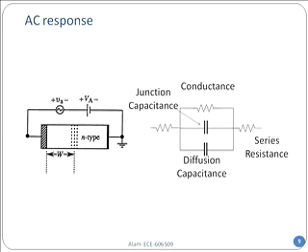And again, in principle, you should have all this conductance at that bias, governed by the DC bias. The junction capacitance, well, that I might have, but I will not have a diffusion capacitance here. And that's what I want you to understand, why I don't have a diffusion capacitance. And therefore, this device is actually very fast.